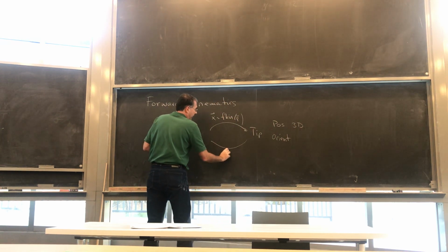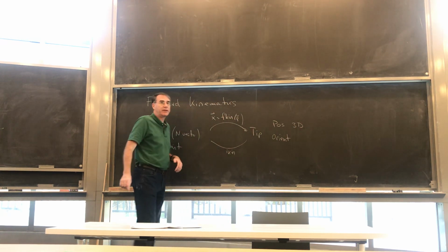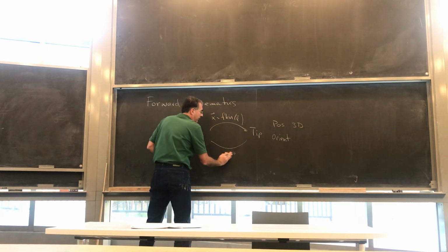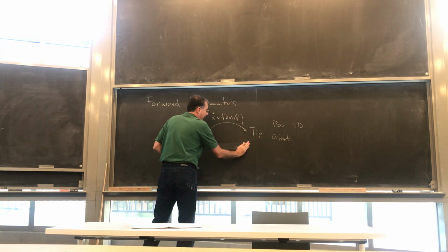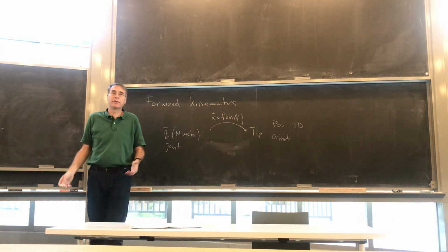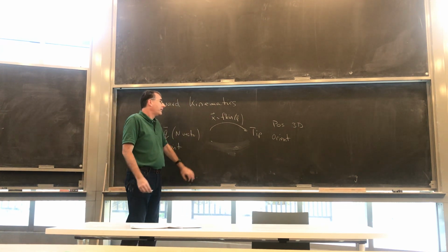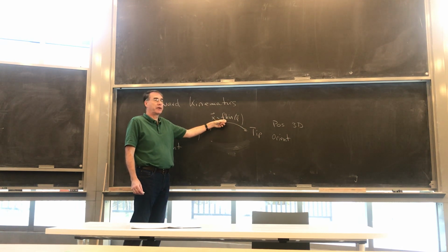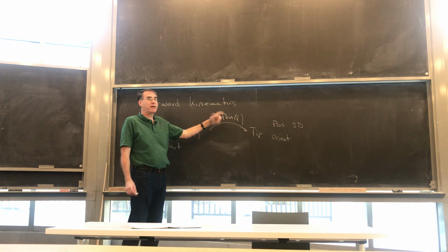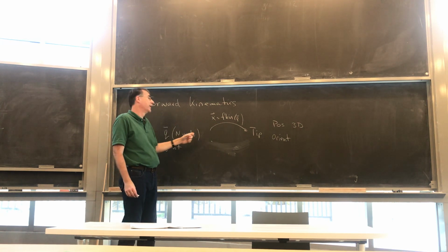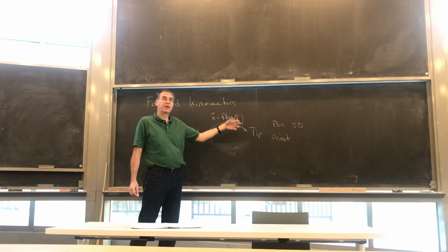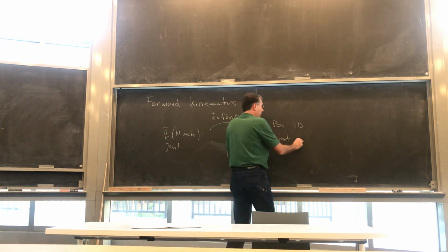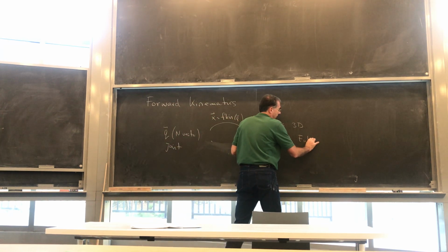There's the opposite, the ikin, the inverse kinematics, which basically says if I want to have a tip here, what do my joints need to be? We'll do that one kind of next week. So I'm going to stay away from the inverse kinematics because you can't solve both at once. I keep saying fkin, it is my abbreviation for forward kinematics. It is basically a function. It's a one-to-one mapping. The nice thing is it's unique in this direction, which is why it's easier to start here. Orientation. We can do Euler angles.